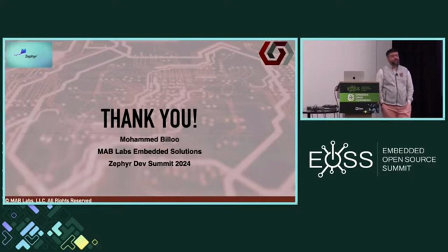I'm implementing OpenAMP with Zephyr on the i.MX 9.5. There we can use the boot fuses to launch Zephyr from the QSPI. And then the idea is to implement remoteproc the other way around. But as a stopgap right now, we're just going to boot Linux first and then the other way around. But the notion is that you have this fast RTOS booting, doing your pinmuxing, and then 10 seconds, 20 seconds later, whatever, depends on your Linux, that comes up later then.